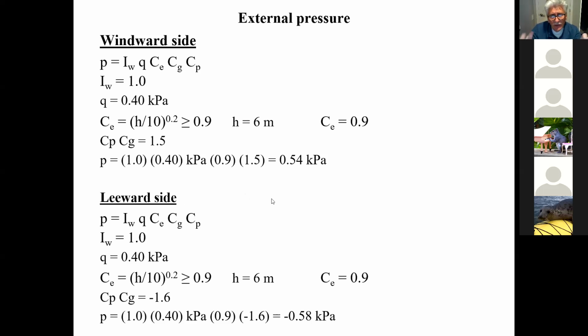If you have two different tributary areas and you end up getting two different Cp values, I suggest you evaluate both and take the higher value. Follow? Makes sense. And then I would just design it for one girt and make the same girt all over. Okay. Perfect. Sounds good? Thank you. You're welcome.